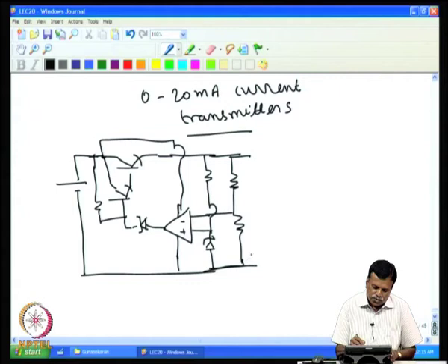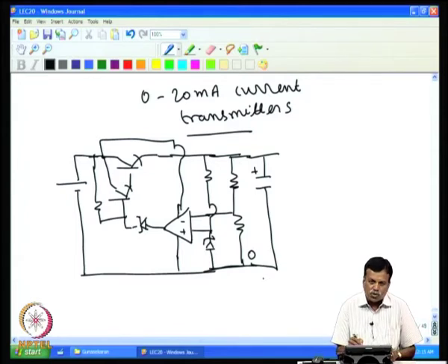All that is required is that one has to get a steady voltage across these 2 points. Of course, we need to have a capacitor, and this capacitor also can be electrolytic, no harm, because even the leakage that develops is not a serious issue. So, one can have the regulated voltage, and this can be even a conventional regulator. The regulated voltage has to be slightly higher.